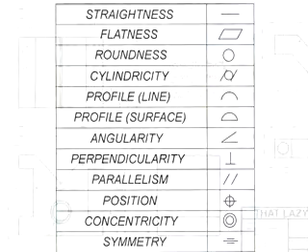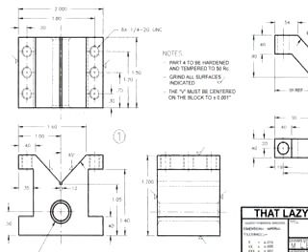And if we had used this symmetry to tolerance the centering of the V on that V block drawing that we were looking at the start of this, well, we could have dispensed with that awkward note that was trying to tell us as clearly as possible that the V had to be centered on the block regardless of the block's width.